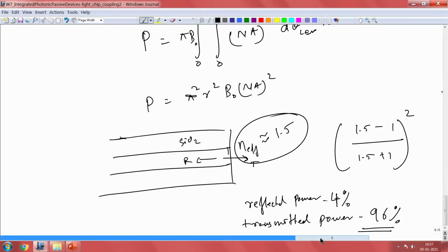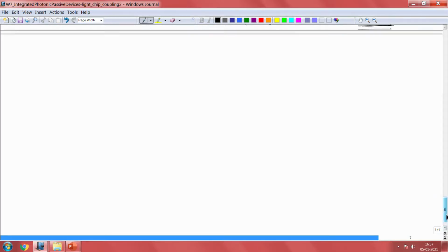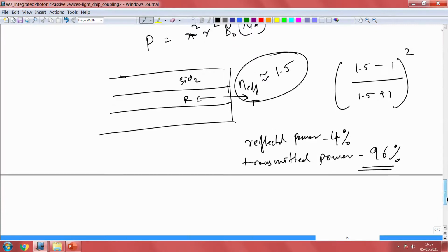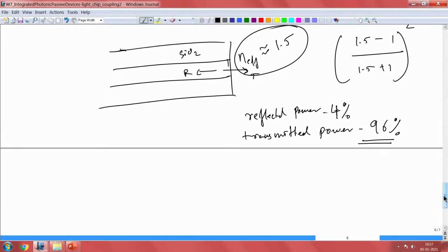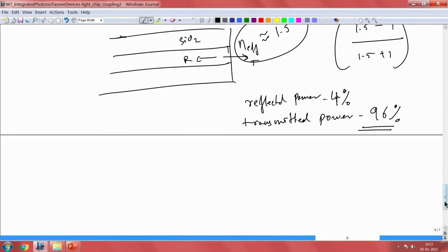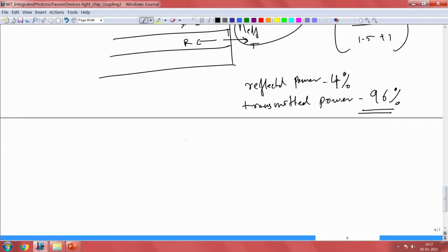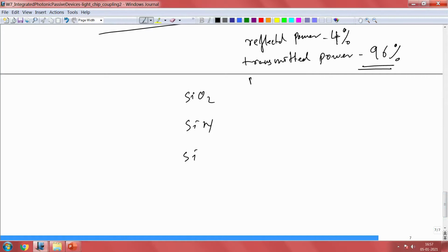This is a challenge when you take high coupling between high refractive index platforms. For example, coupling light into silicon or silicon nitride is challenging compared to coupling light into a circuit with silicon dioxide. So, there is silicon dioxide, there is silicon nitride, and there is silicon. Silicon dioxide refractive index is 1.5, and this could be 2, and this is 3.5, and the coupling